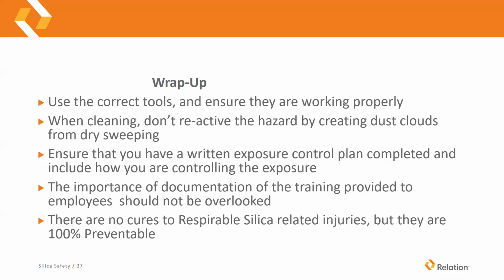You need to get your signatures, and your employees that are exposed to silica need to be able to talk a little bit about what those hazards are and how they can harm them. And last, there are no cures for respirable silica-related injuries, but they are 100% preventable.